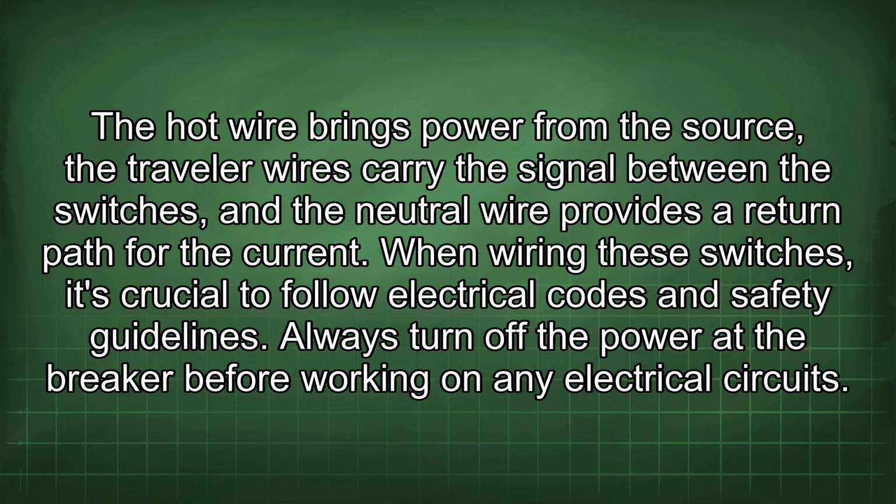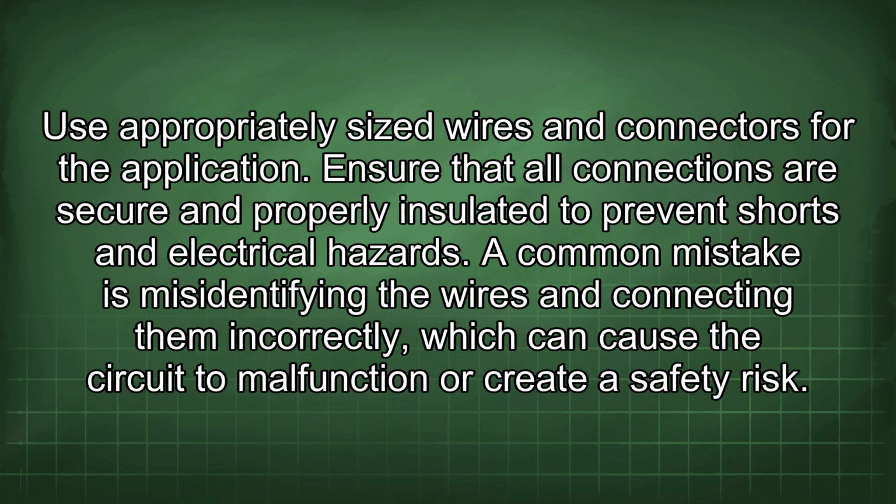When wiring these switches, it's crucial to follow electrical codes and safety guidelines. Always turn off the power at the breaker before working on any electrical circuits. Use appropriately sized wires and connectors for the application. Ensure that all connections are secure and properly insulated to prevent shorts and electrical hazards.